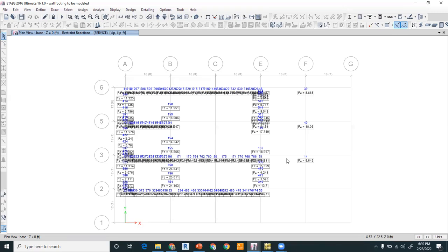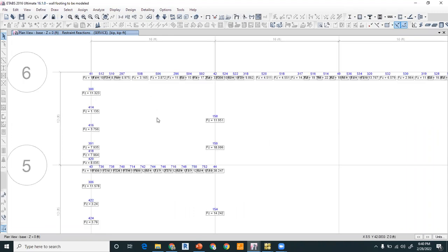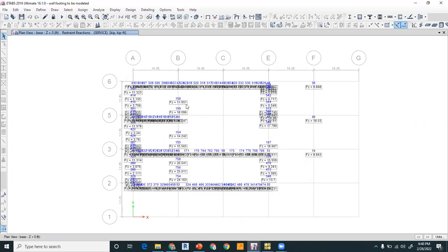So you will learn in this session, and you can apply it on RC buildings or plazas as well, right? The procedure for the strip footing is that you have to calculate the length of the strip you want to provide, and from the length you have to calculate the required width to transfer the load into the soil, right? For the interior walls, you have to calculate it separately, and for the exterior you have to calculate it separately, right?